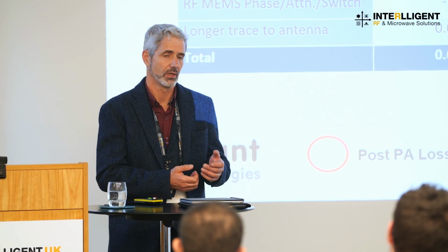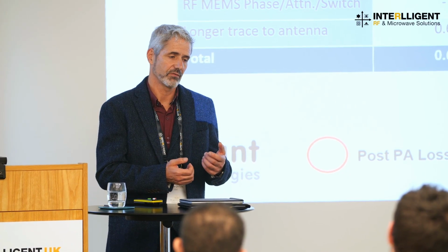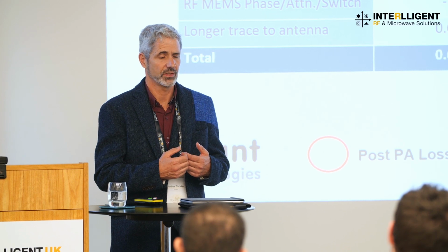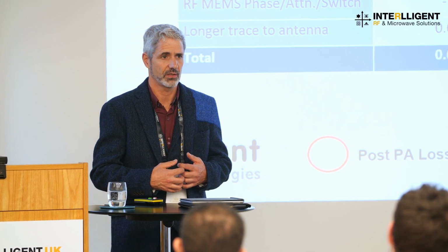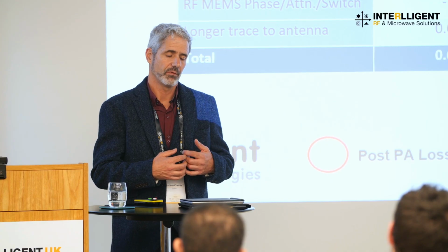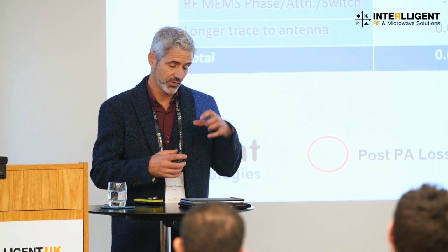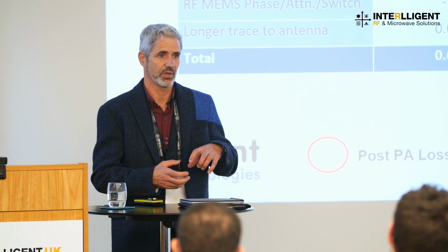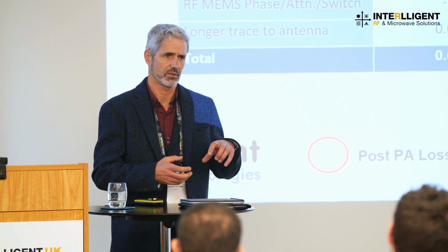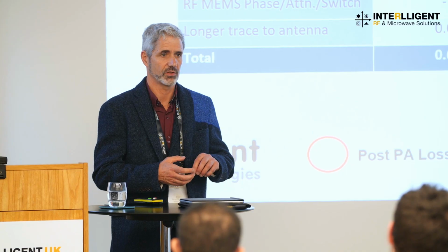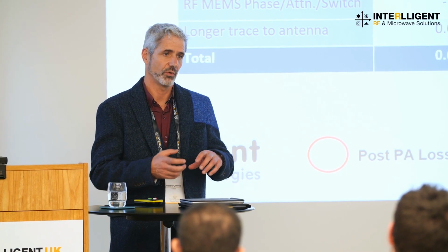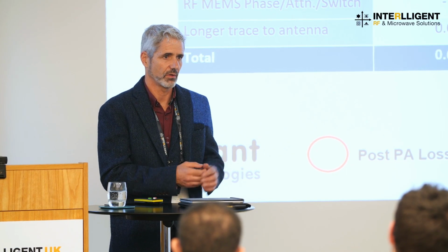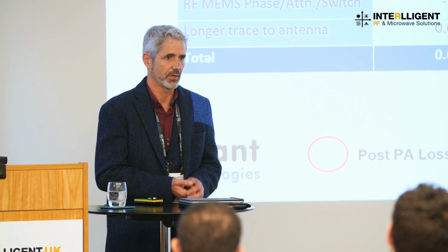So we use a conventional LNA, but it's of our own design because we played some tricks in the LNA to reduce the loss before the LNA, within the chip, so we can get the lowest possible noise figure. And so we think our receive lineup is lower power and smaller size than what's on the market today because we've got lower effective noise figure in our LNA.